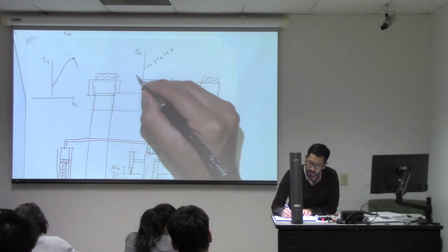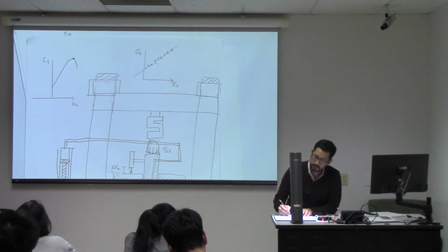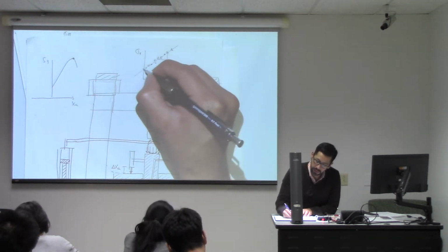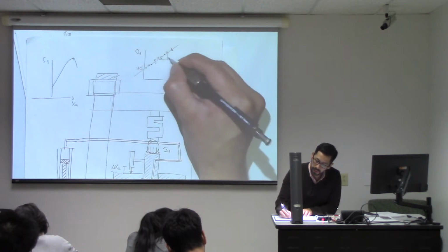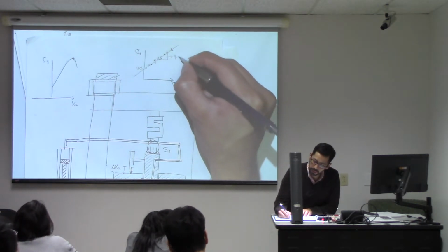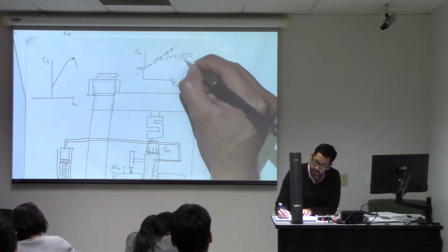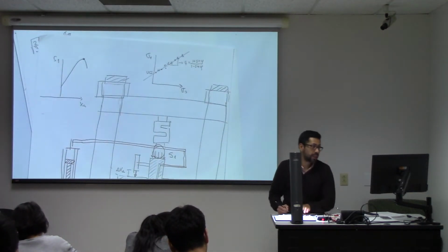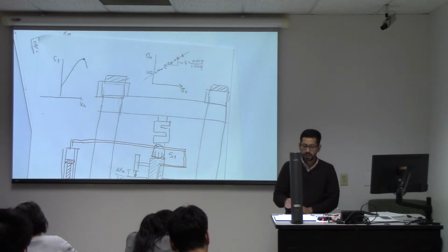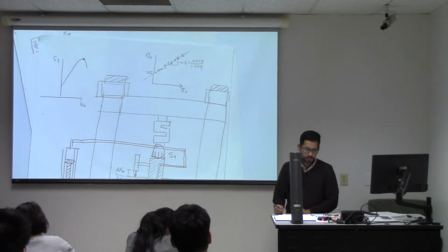And all of that is going to allow you to fit a line where this is UCS, and this is, you can call it variable Q, (1 plus sine of phi) over (1 minus sine of phi). And you can do the same thing with J2 and I1.